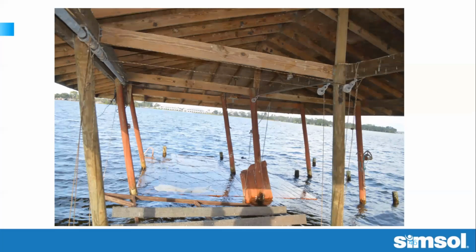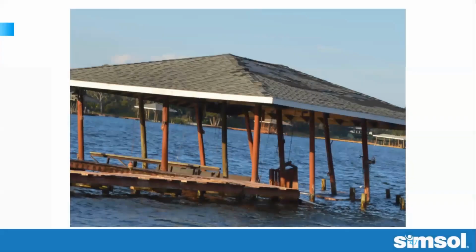And again, take a look out here at the structure. There's no lateral bracing here. There's no pieces connecting the piles or the poles to the supporting horizontal members of the roof. So that makes the structure inherently unstable, and when you get enough wind, it will rack the structure. And again, notice the wind damage here.